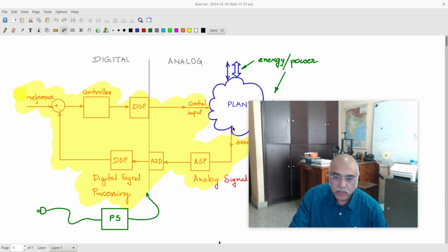We sensed using some sensor, some transducer, and the output of the transducer is an electric voltage or current, and that is passed through a zero and span circuit, so that you get an output from the zero and span circuit which is compatible to be processed through an A to D. If there are offsets, you are trying to remove the offsets.